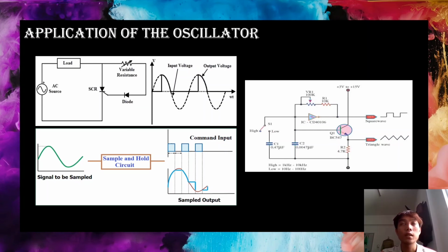In electronics, a sample and hold circuit is an analog device that samples, like captures or takes, the voltage of a continuously varying analog signal and holds it. It locks its value at a constant level for a specified minimum period of time. Sample and hold circuits are related to peak detectors, which are elementary analog memory devices.